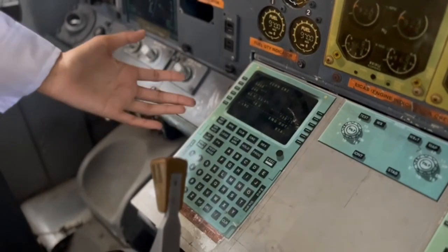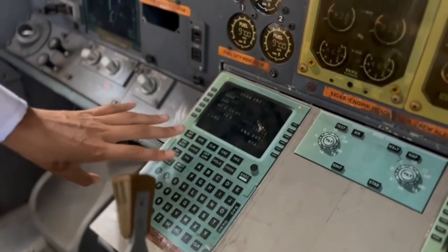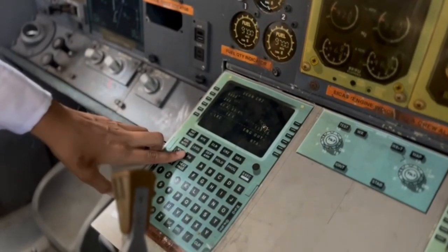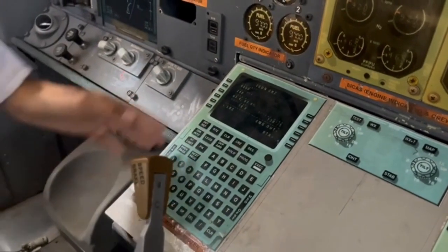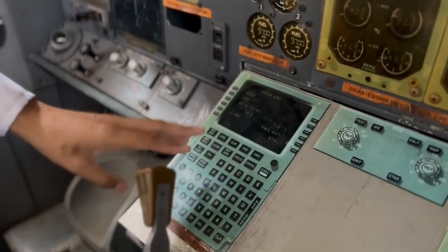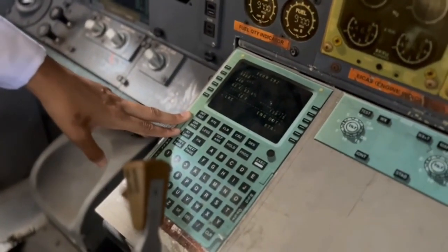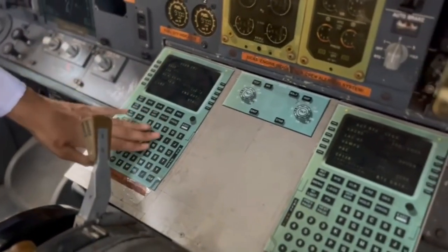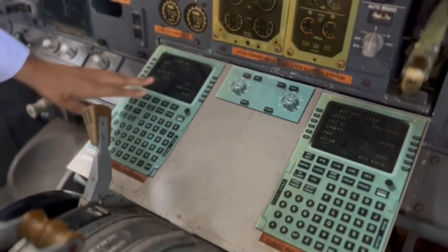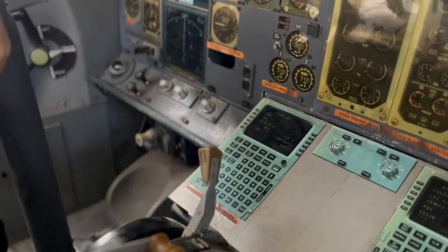So let's look at a discussion about FMS. First, it can manage flight planning. Pilots can input waypoints, altitude, and speed using the CDU, control display unit. Second, pilots can improve accuracy and efficiency, as it helps maintain optimal flight paths and fuel usage. It is also used with the basic digital display, and the FMS sends data to the navigation screen similar to what is seen in newer glass cockpits.